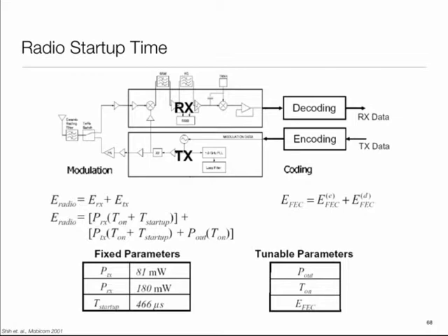So what we see here is that the energy has to take into account not simply how much time you transmitted, but also the cost associated with the startup. If you are doing lots of work all the time, startup cost is going to disappear and get amortized. But if you are doing a relatively small amount of work occasionally, then this becomes very significant. So for systems which are designed to operate in settings where they're running very sporadically, this startup power matters quite a bit as well.